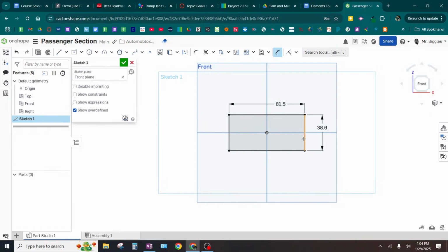So how do you estimate the radius of those? You ballpark it. You can take your calipers, open them up, and put them on there to try to capture how big the curve is. What I'm doing here is lining up one edge of the calipers with the edge of the wood, and ballparking the other edge to be about where the wood transitions from being curved to being flat. It's a little ballparky, but it looks like it's somewhere around 9 or 10 millimeters.